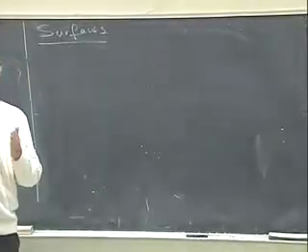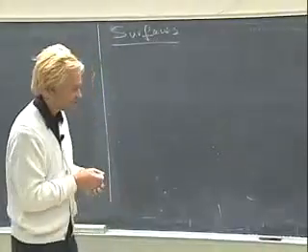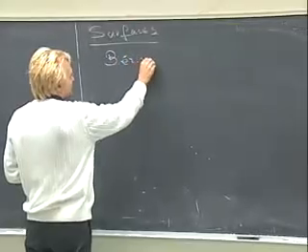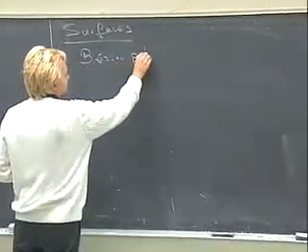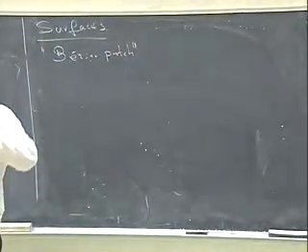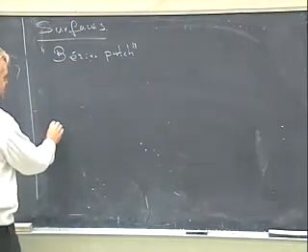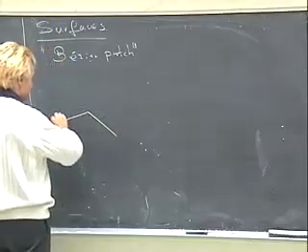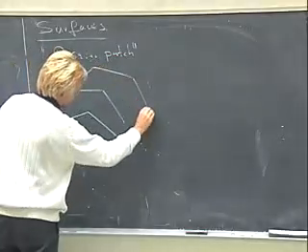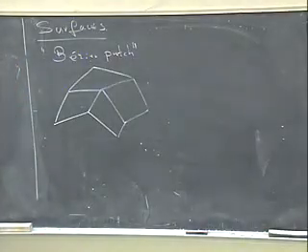So first, there is this Bezier surface and there is this B-spline surface. Logical extensions of the Bezier curve and B-spline curve. So there is a Bezier patch. Okay, it's called a Bezier patch. Again, the idea is I have a little polygon that resembles the shape that I want to represent. So there is something like a control net, it's called. Looks like this. Okay, it's a little tent.